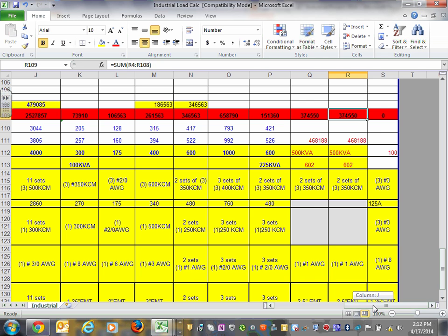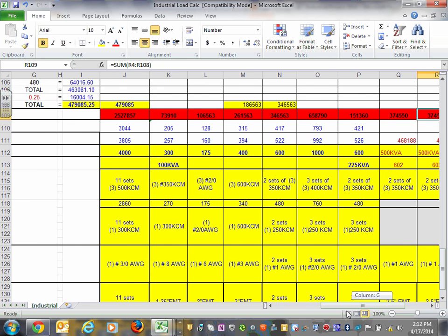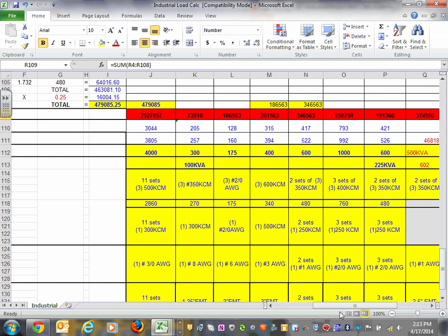Okay, so now after you capture it, most of the equipment that we size, guys, is based on the amps. Then I divide by my system voltage, which is 480/277. So you can see the math there. I'm taking that cell at the top and dividing it by 480/277. Here you can see that cell right here.